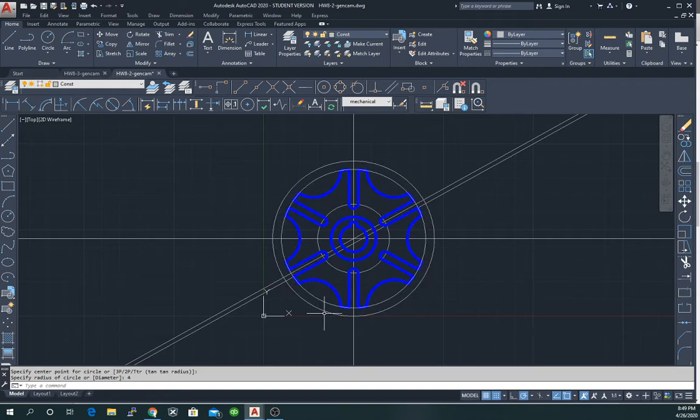And if you take note, this is exactly the same as the radius of the outer edge of the part. And if you actually walked through the book and went through the instructions of the book, it had you create this initially. The next line I'm going to create is the actual construction line, and that's going to go from the intersection of the bottom of the circle and just make a horizontal line. This is going to be our guide for our construction layer.